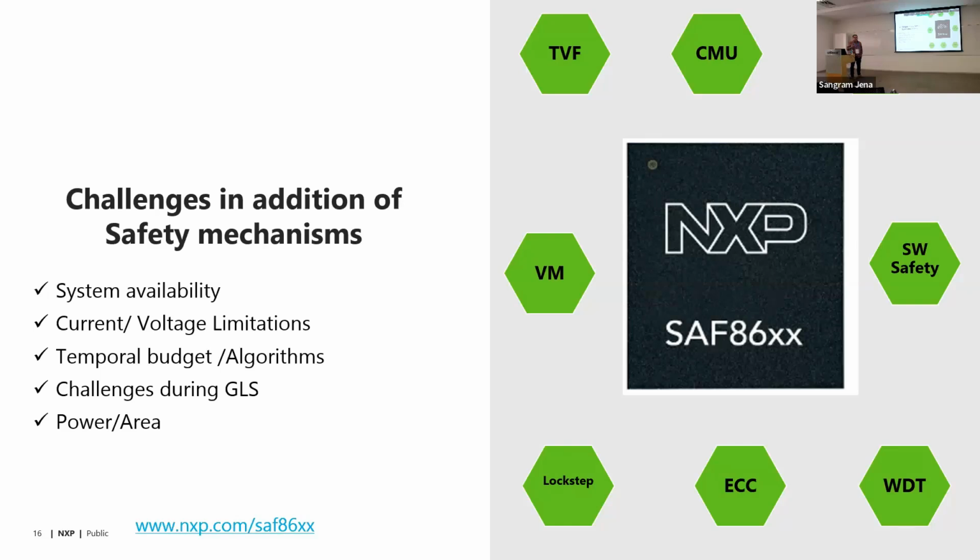Whenever the chip is undergoing any kind of self-test, that duration is one where it is not doing its main job. So you can have repeated self-testing during the radar cycle, but that means the radar is not doing its main job during that time.